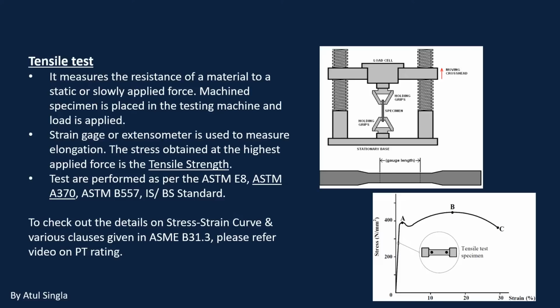With increase in load, stress and elongation with respect to this stretching, this kind of curve will always be there. Up to a certain point, the material will keep on coming back to its original position, which is called the elastic limit. At some point it will start showing permanent deformation. Again, up to a certain point it will keep on elongating, and after a certain limit it will break. So this kind of testing is done.